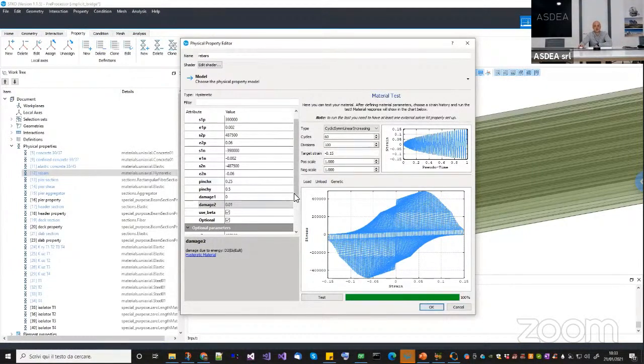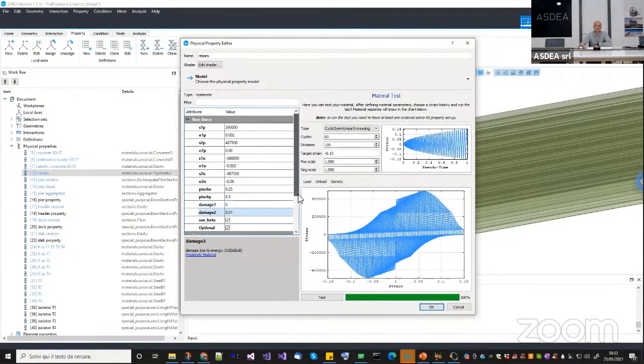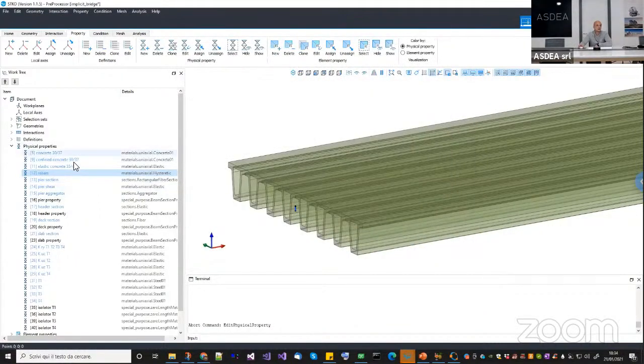And it is the only one that you can use to simulate cyclic damage when you use a fiber cross-section, because actually no concrete model is able to model this kind of cyclic degradation, because basically it comes from the rebars, okay? And if you use materials like the steel 01 or steel 02, they don't have it. From what I remember, the only other material that includes cyclic degradation for steel is the reinforcing steel material. The problem is that it has some convergence problems. So when I want to include cyclic degradation for steel, I always choose the hysteretic. Okay. So here we are done with the uniaxial material.